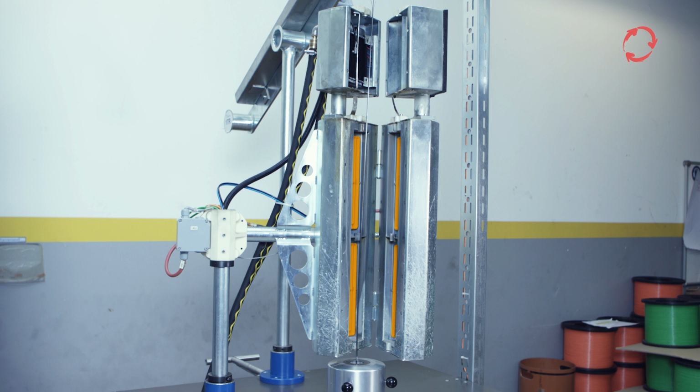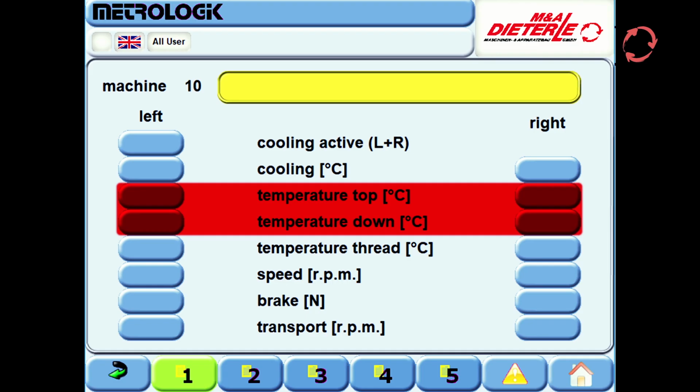The heater is preheated before the process begins. Once the target temperature has been reached, the winding process can begin. The target temperature must first be set in the process parameters of the respective program. This is described in Chapter 2.4.